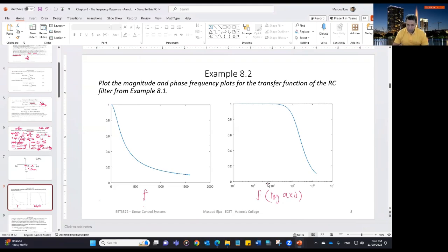Semi-log x divides the interval into equal parts, and it is easier to see the change in the response, even if the response changes only towards the lower frequencies and you're going up to very high frequency, you will still be able to see the response properly.